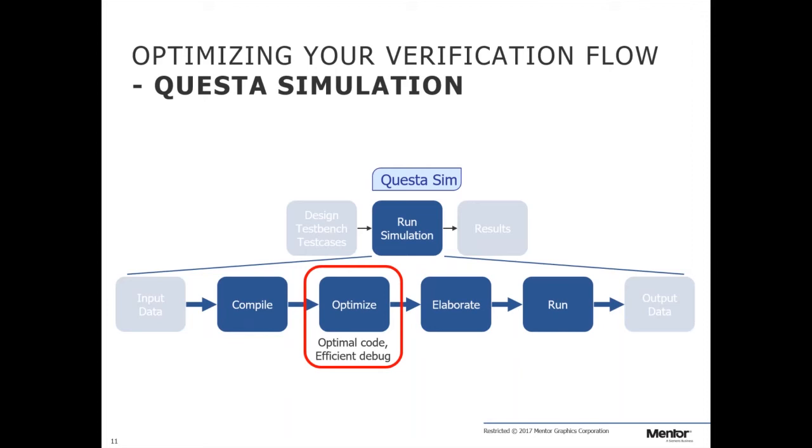And so it does all kinds of software optimization things like inlining function calls, merging parallel always blocks that have the same sensitivity list, maybe getting rid of signal aliases. So if you have 15 different names for a signal, it might want to collapse that down to one signal that it has to keep track of rather than 15 different things.